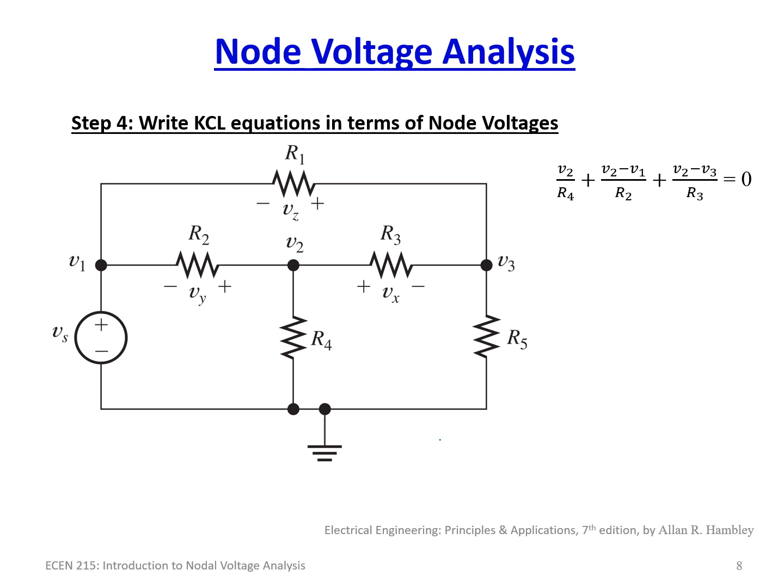So let's just draw this out. We have a current going this way, we have a current going this way, and there's also only 3 possible currents, all leaving. So let's ponder for a moment. What do you think this is going to be? Well, what about this one? Let's first analyze this current here. That's easy. It's V3 over R5. What about this current right here?